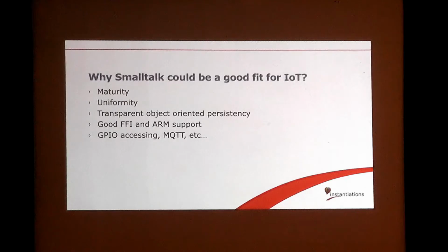We have good FFI, at least for VA Smalltalk it's really good. We have async support. It works on ARM. And then we also have GPIO access, so we have wrappers for the C libraries for managing the GPIOs. We have MQTT implementations, and all those are libraries that are usually necessary if you are doing some serious IoT.